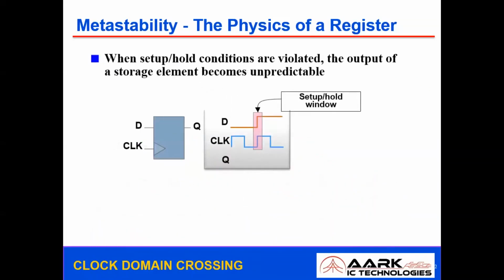So basically, any flip-flop is a cascade of two latches, right? And both the latches are level sensitive, and when they are connected together, your output changes at the edges of the clock. And during the edges of the clock, your data needs to be stable in order to have proper data at the output and in order to avoid the loss of data. And this latch avoids the metastable issues. So what is metastability? Metastability is nothing but violating the setup and hold conditions.